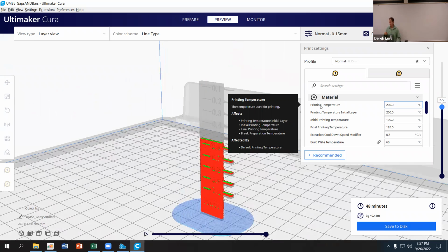Now, there are things you can do with controlling the temperature and the layer height to improve the interlayer adhesion, but typically at the cost of print time. So if I use a slower print speed with smaller layers, I can usually get better interlayer adhesion. It's never really going to be as good as it is in all directions. But again, then you're taking a lot longer to print. So you can tune those things, but it's hard to get it perfect.